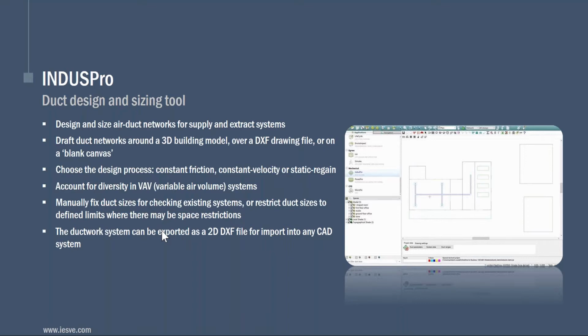Again, once you're done with the design sizing, you can export that data as a 2D DXF file for other CAD systems. But as I said, we are working in the background to ensure that you can get the data out of IndusPro and bring it to a Revit MEP environment, so that you don't have to repeat, or copy and paste data from one platform to another. So that's PiscesPro and IndusPro. That's the summary for both these tools.